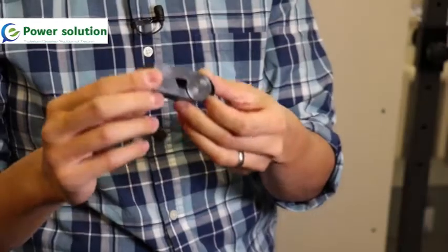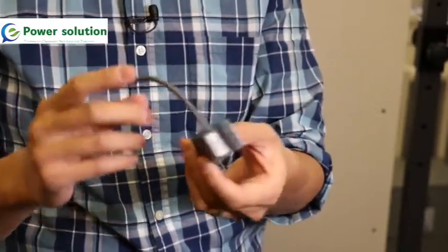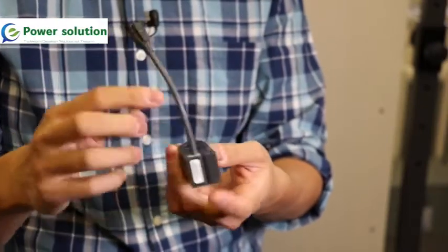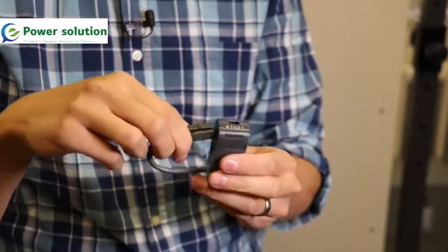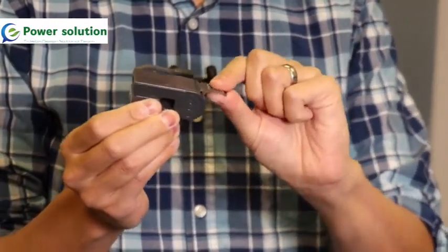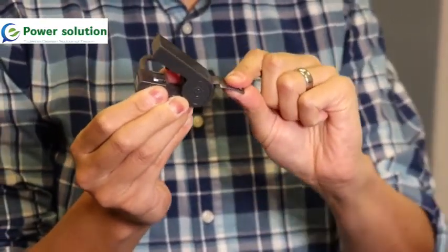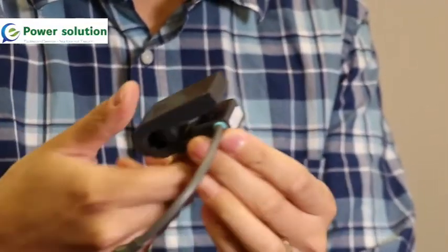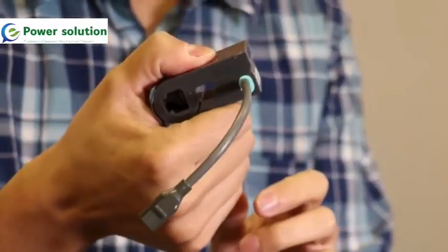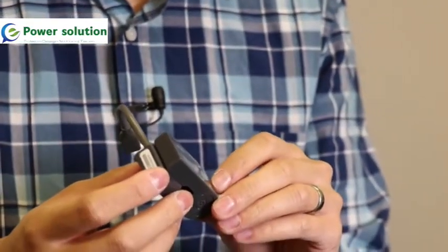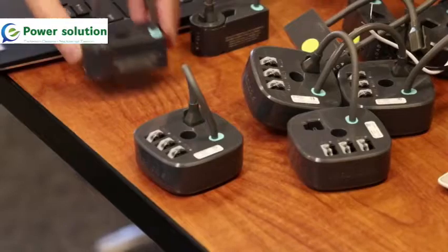The first component of our system is the Vertigo Smart CT. It has a digital data cable that comes out of it to record the sensor measurements. Each one also has a socket that you can plug the cable into. There's a flexible hinge on the back where you take out the tab and you pull it back to release the clamping mechanism. When installing, you want to open the clamp, put it around a wire, and close. And once you hear that snap, it's closed and you're ready to measure energy. The install kit that you receive from Vertigo will include the correct number of sensors for the panel that you're installing on.